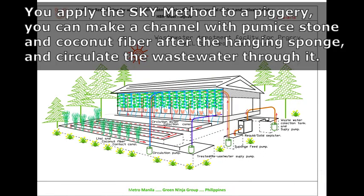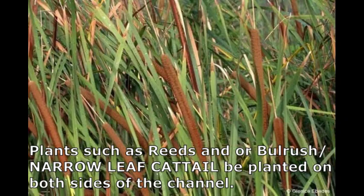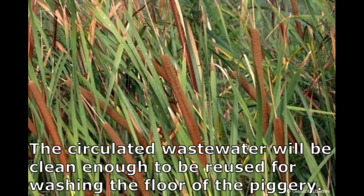You can apply the sky method to a piggery. You can make a channel with pumice stone and coconut fiber after the hanging sponge, and circulate the wastewater through it. Plants such as reeds, bulrush, or narrow-leaf cattail can be planted on both sides of the channel. The circulated wastewater will be clean enough to be reused for washing the floor of the piggery.